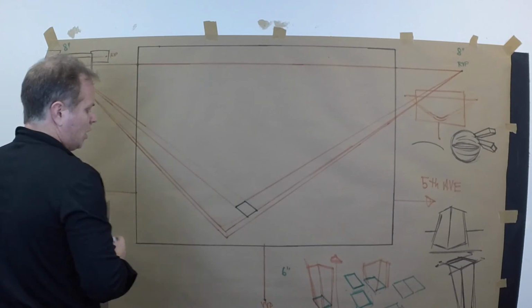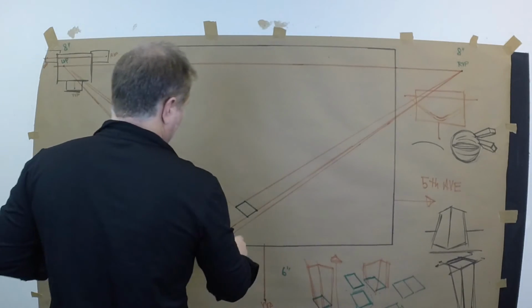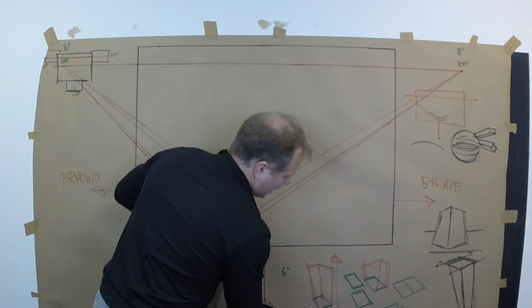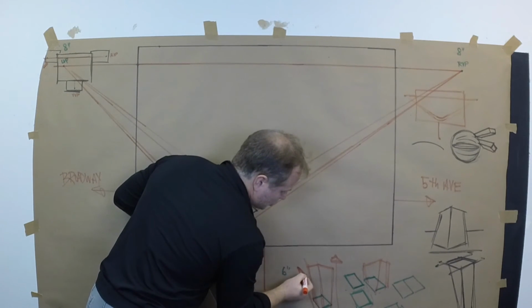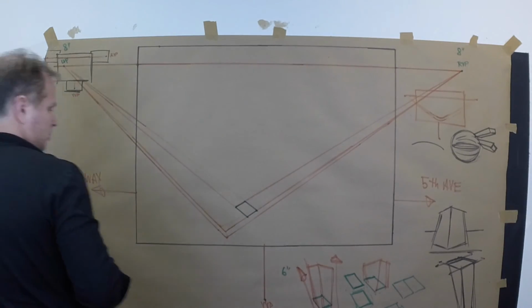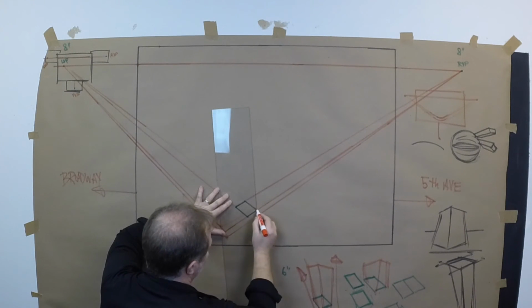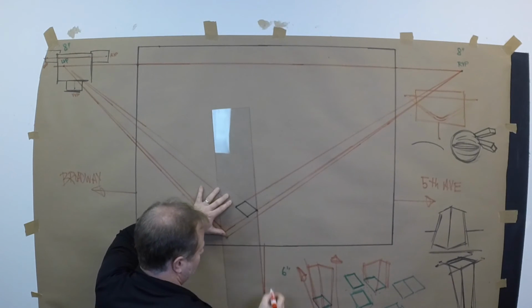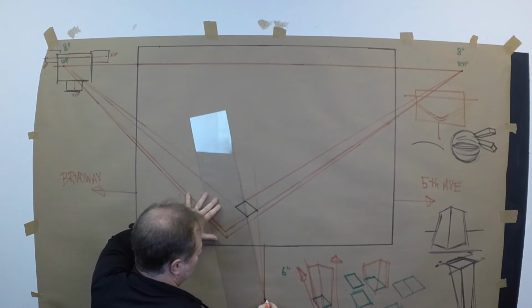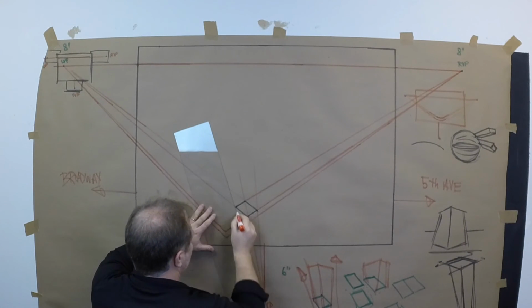All right, so now from the vertical vanishing point, we need to draw up from here, this point here, up and give elevation, a rise to our structure. Now we're going to go up from the ground. So from the vertical vanishing point, from the VVP, it's got to go through this corner here, up some, go through the front corner here, up some, and then from the left corner here, up a little bit, right through here.